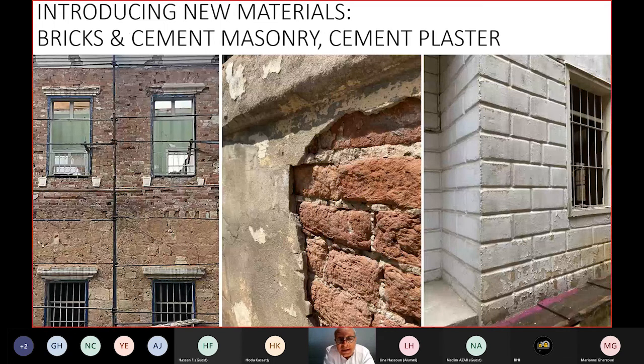And the cement masonry units, CMU, which will be prefabricated and will complement construction. We will use this as a replacement for the famous Ramleh sandstone. And instead of Ramleh sandstone, we will use cement blocks that will be all molded, all cast with specific shapes and specific dimensions. Thus, it will be very easy to construct with it. And these materials will be, of course, plastered or not plastered with cement plaster and then lime washed.